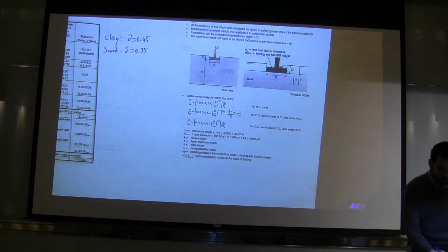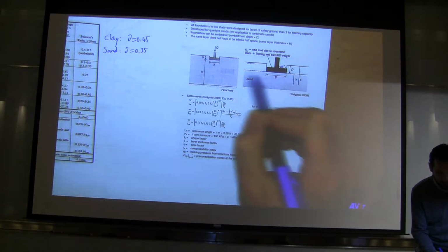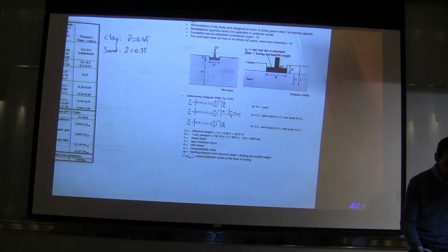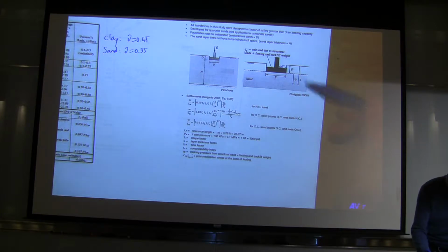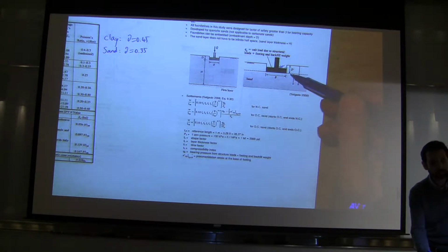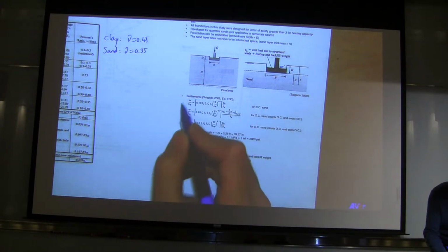So basically, all the loads that are applied at this dotted line elevation, everything on top of that, are QB. And then there are these other two depth variables too. So Z is defined from ground surface, ZF is defined from the base of the footing, so keep those in mind too.